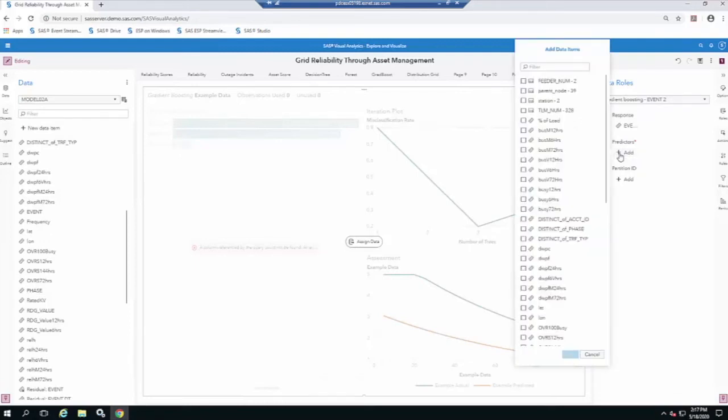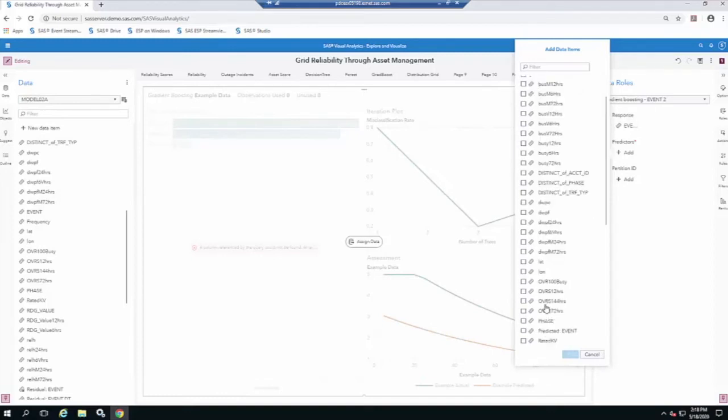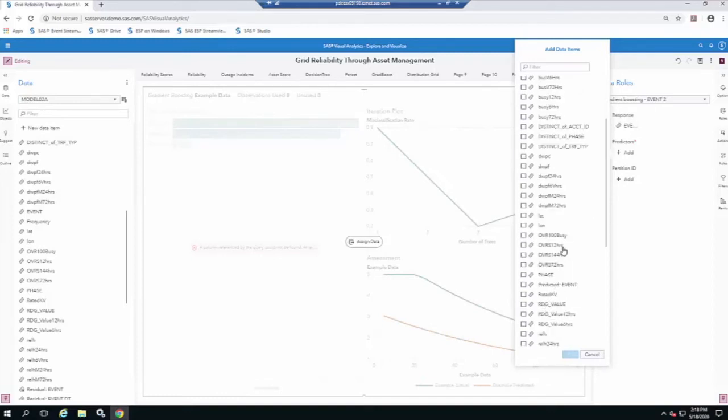Those are running values that I've bucketed back 72 hours. And that bucketed information represents time fields of values based on load, variance values, median values, maximum values, and also weather data with those same bucketed fields. I also have indications in here when the transformer has gone over 100%, over 120, 140%, or over 150% of